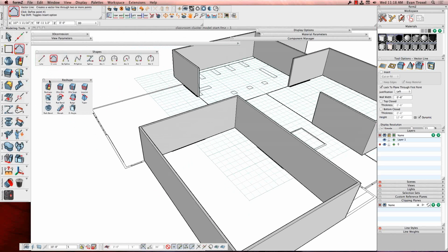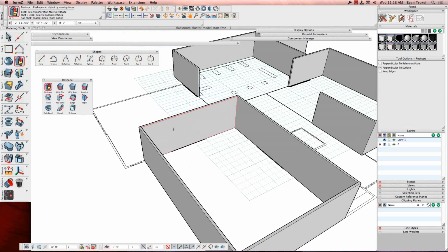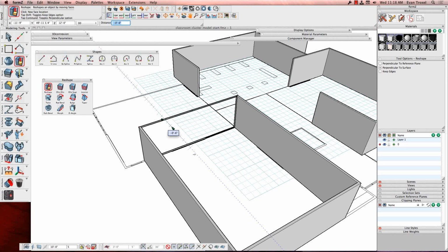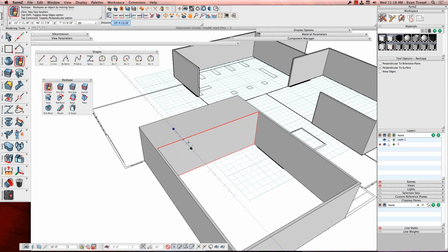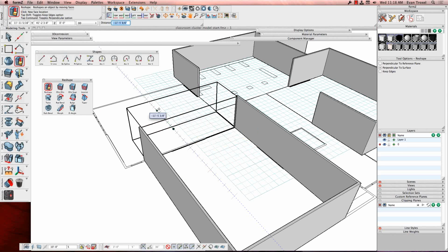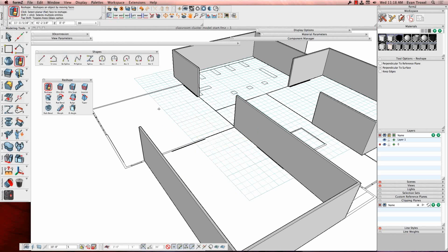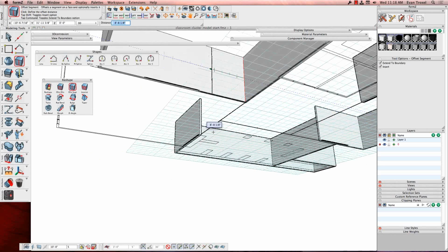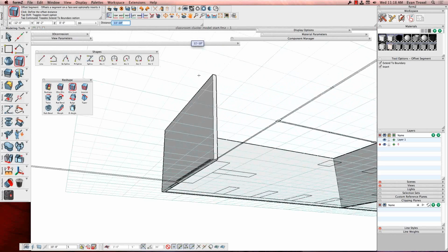So what I might do with this rectangle to reshape it real quick is let me pull out my reshape palette. So now I can just blow a wall out, and this brings up an important thing, another reason I really like working inside FormZ is that it uses live Booleans. All right, so I can push a face, and it just pushes that out, and now it's gone. Or I can offset a segment. In this case, I'm going to offset this segment back and snap to my wall that's under there.